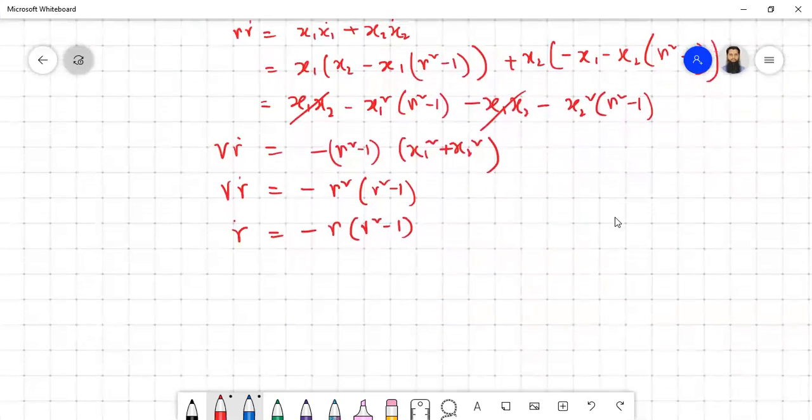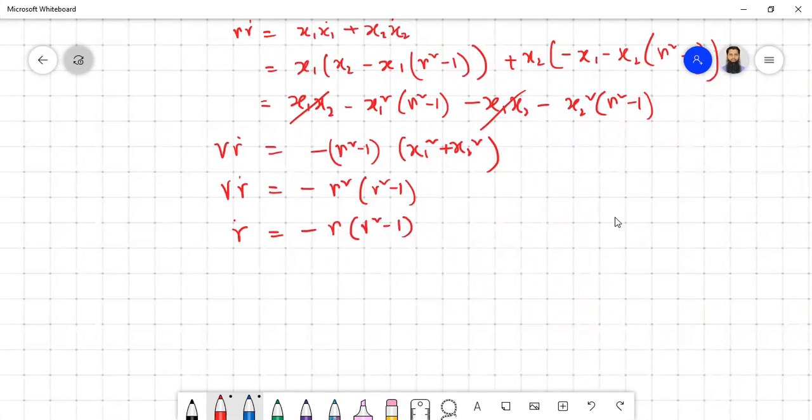Now, what we know is that once a trajectory is on the limit cycle, it will always try to remain on the limit cycle. Okay, so this is a trajectory. So whether there is a limit cycle or not, the first thing is that for the limit cycle, r dot should be equal to 0. That is possible, r dot equal to 0 only if r equals 1.